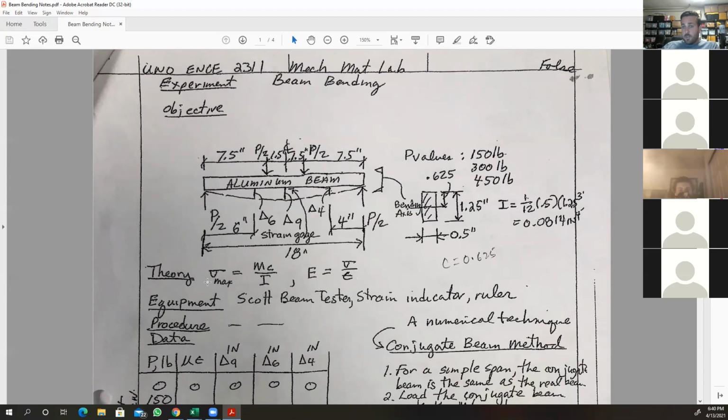And if you're trying to calculate the maximum stress, what I said for torsion is the same way. Maximum stress is developed at the outer surface. You have zero stress development at the neutral axis. You have zero deformation at the neutral axis. As you go further away from the neutral axis, you start seeing more stress and more strain developing on your member. Are we okay so far? Yes, sir. Okay, good.